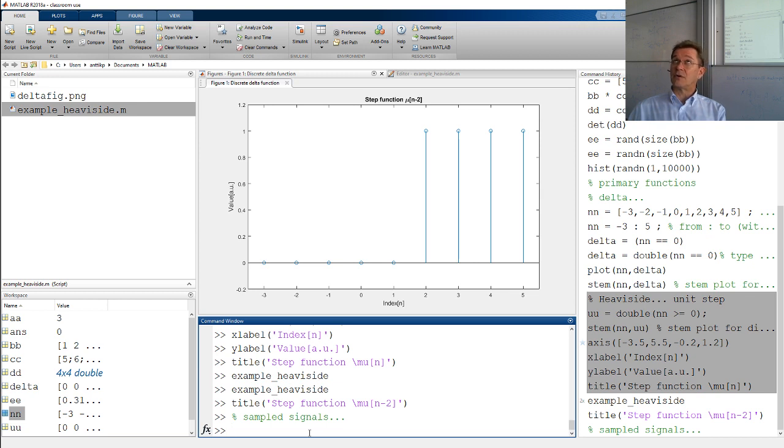Let's try the 44.1 kilosamples per second, although that will be a little bit overkill. Another good number would be 8,000 samples per second. That's good enough for speech. Not good for music, but speech, perfect. Human voice is in hundreds of hertz, and then you add some harmonics to get these hard consonants on it. So 8 kilosamples per second should be enough for most of the human speech.